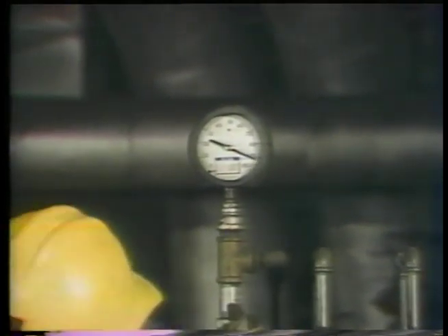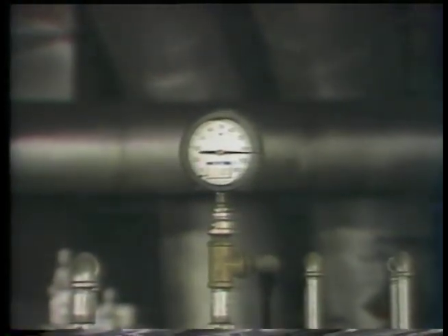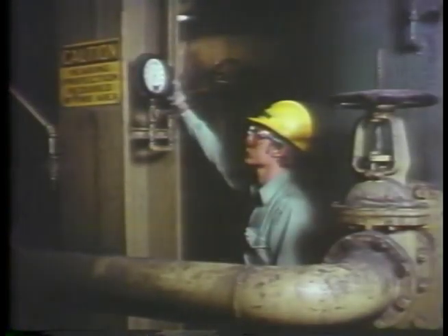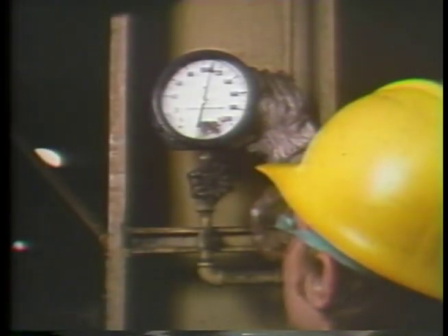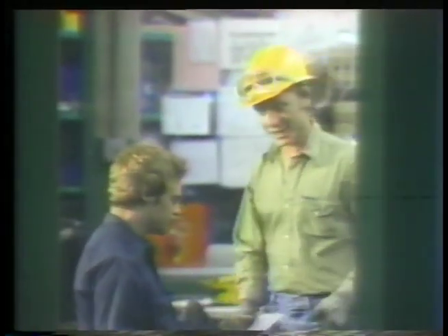Once this is done, you should inspect the system and make sure that it is operating normally. This may involve checking another gauge upstream or downstream of the one that is off scale. In this case, the operator discovers that the actual pressure is too high for the gauge, which was off scale. So, he reports it to the instrument department so that they can replace it with one designed to handle the pressure. An instrument technician will then be sent to replace the gauge.